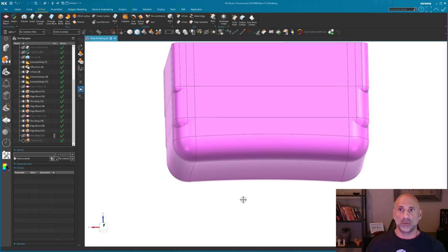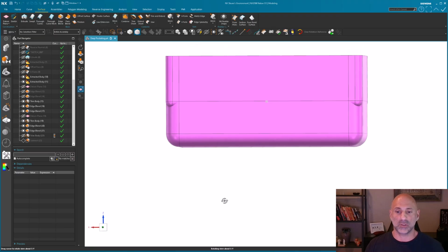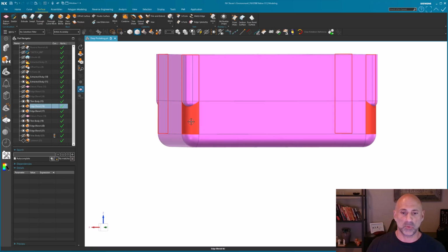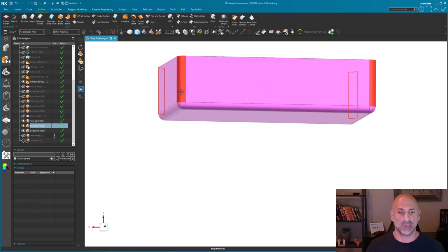Now, once you've determined that, depending on what you need, you're going to potentially have an additional step or two on the way out because you need to have some lightweighting done on the part. So you have an additional machine setup that looks like this, where I have a smaller ball coming in, and then another machine setup that looks like this, again, another smaller ball. So depending on the depth of the pocket, you're going 2, maybe 3 additional steps. Highly unlikely you're going 4 unless there's some very specific reason you're doing that.